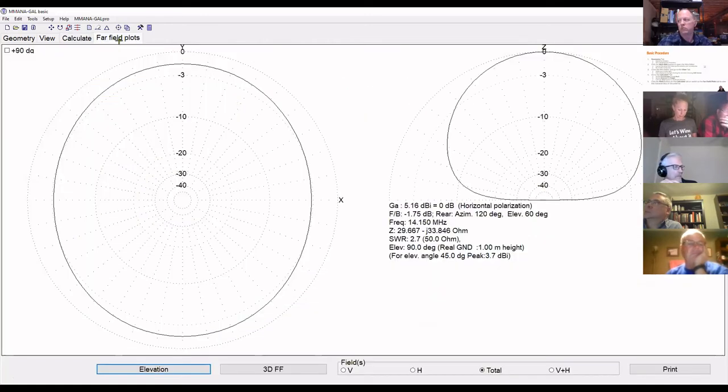And if we go look at our far field plots, we have a cloud burner, but it's still putting out positive gain as low as 33 degrees. That antenna would work for HF. You'd lose a lot of your power straight up, but it would work.